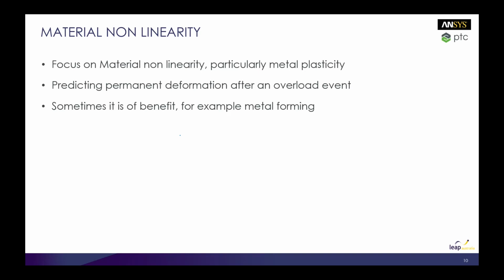Sometimes it's enough just to do a linear elastic material model, so we know what our yield stress is. If you calculate stresses above yield, and if yield is considered your failure point, well, then you know your loads are too great, and your structure will fail.